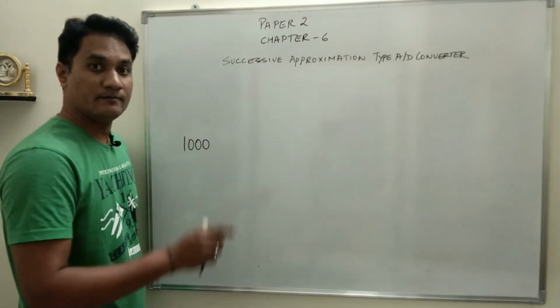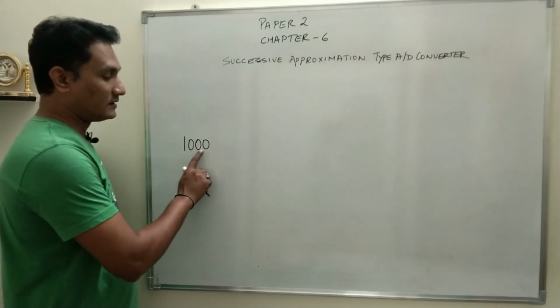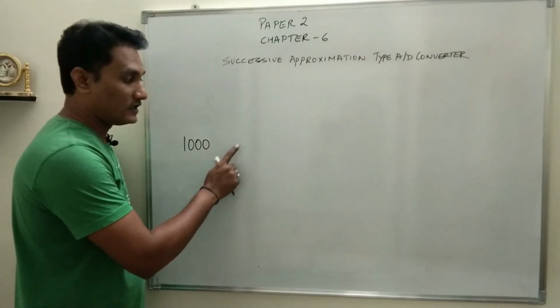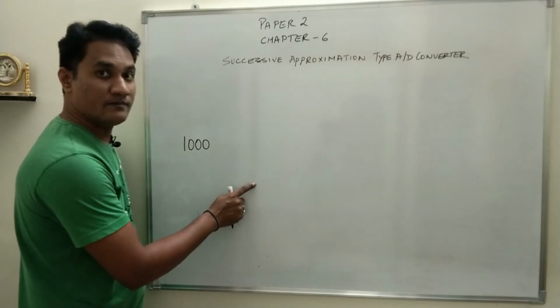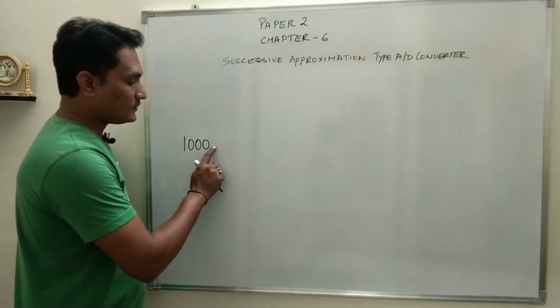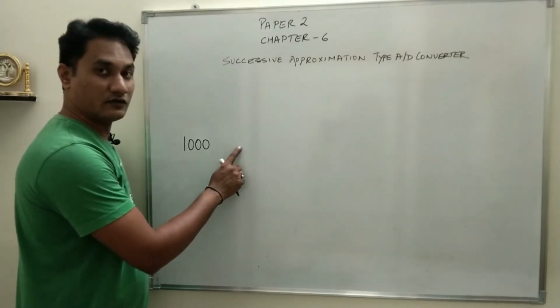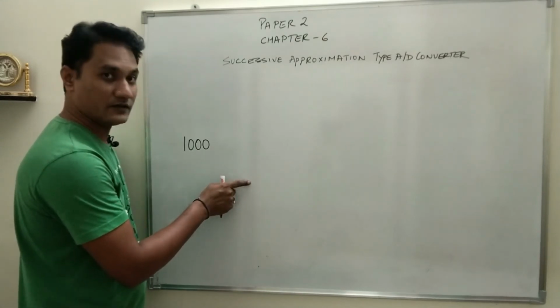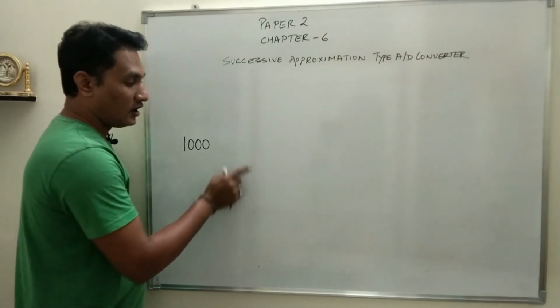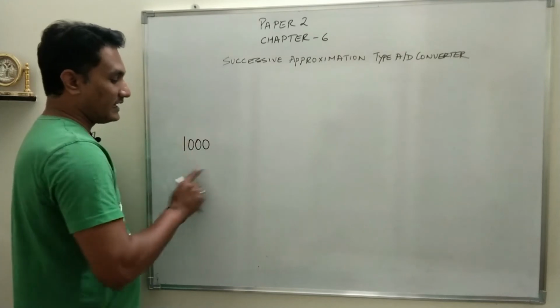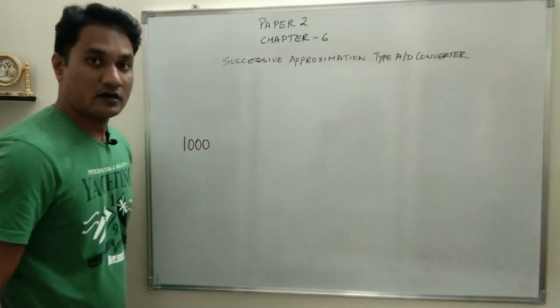Of course, this digital value will be converted into an analog voltage, which acts as the reference voltage. That reference voltage will be compared with the analog voltage, and on the basis of this comparison we will decide whether to keep this 1 or not.